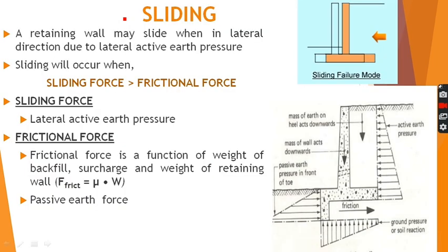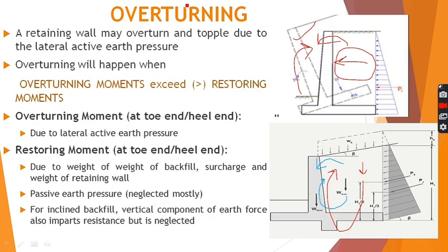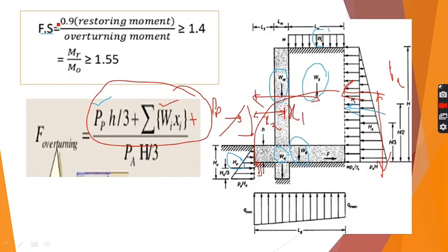So if in any case you are given a problem that you have a retaining wall near your surrounding, or if you are given any retaining wall with given dimensions and soil properties, and you have to check its stability, what you will do is calculate all these forces which are shown here, like WL, WW, WS, etc., and then calculate the restoring moments due to those forces and combine those, and all the overturning moments, combine those, and then calculate the factor of safety.